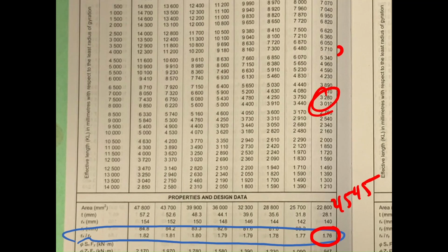So we've talked a little bit about what sections make good compressive resistance members or columns or compression braces. We can see that it's not as simple for us to solve the inverse problem to figure out what section would make the best compression member. But we have tools in the handbook that can help us pick sections that will be relatively efficient. We can pick based on weak axis buckling, which is going to be the case 95% of the time, but we can also check strong axis buckling based on the Rx to Ry ratio. Does anyone have any questions about any of those concepts before we continue on?